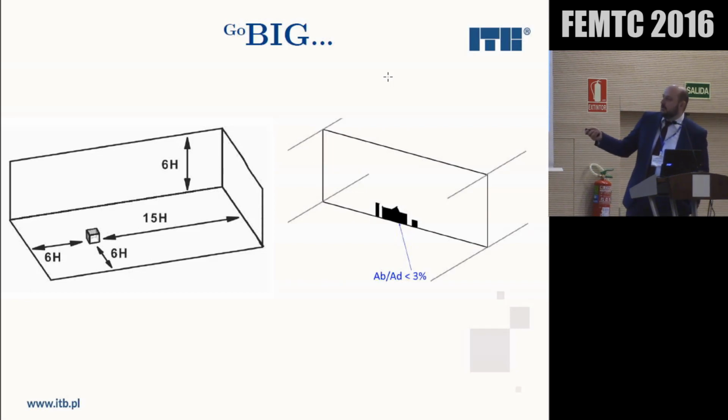You need the room before, so the wind profile can actually catch up with the roughness of the terrain you model, and actually resolve correctly before it reaches the thing you model, because wind is not just a positive pressure effect. Wind is dynamic. Wind is different on different parts of the building. It's a much more complex phenomenon. So you need to give it space to resolve.